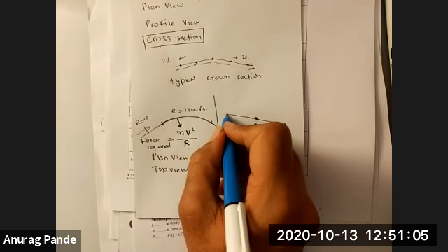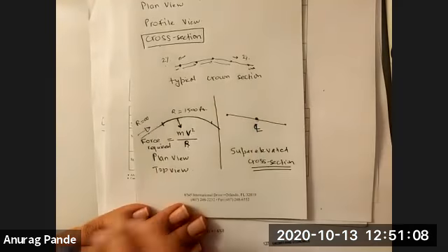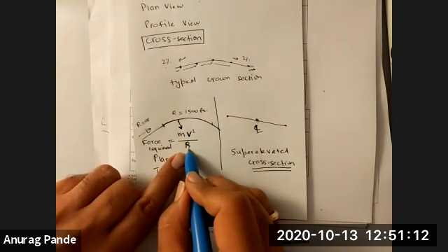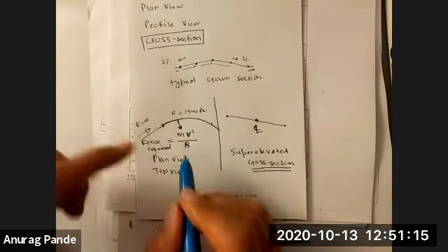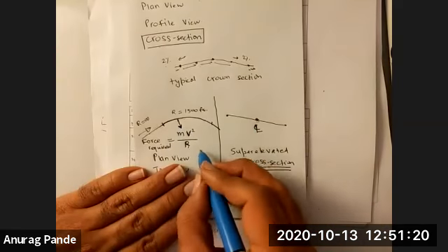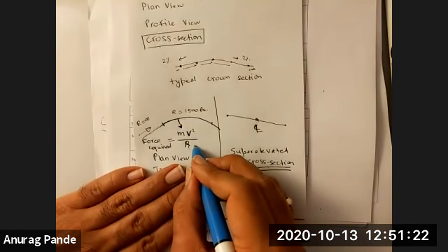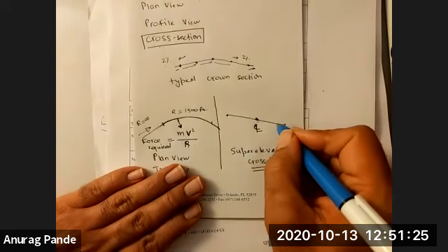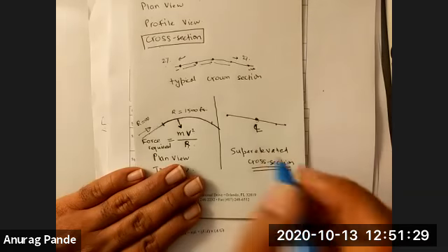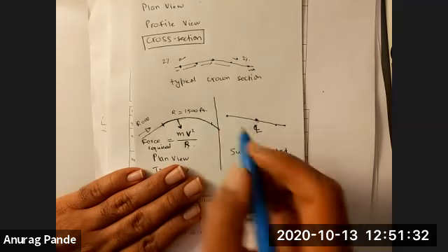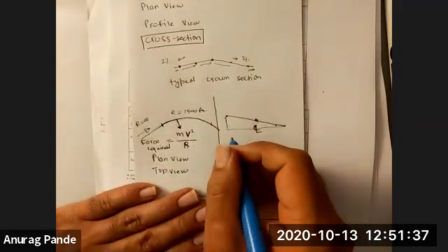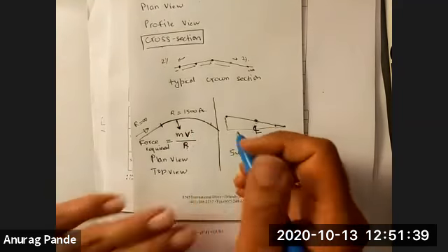Now you can see that this force required is proportional to the V squared and inversely proportional to the radius. So the more inward you are, the closer to the center you are, the larger the force that you require. Typically we look at the inside lane radius, that's our critical radius. The inside lane will be located here, and we raise the outer edge of the road. On a rural road, that slope could be as high as 6% to 8%.